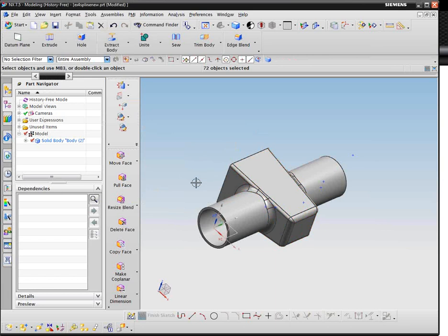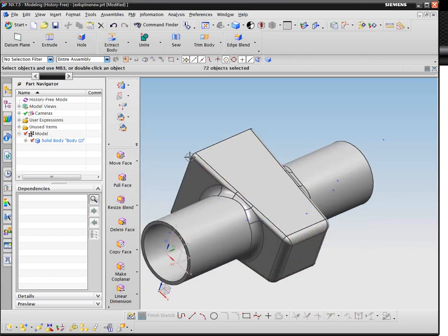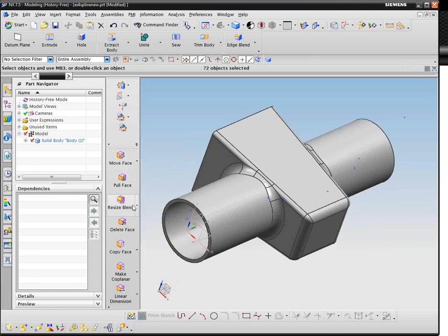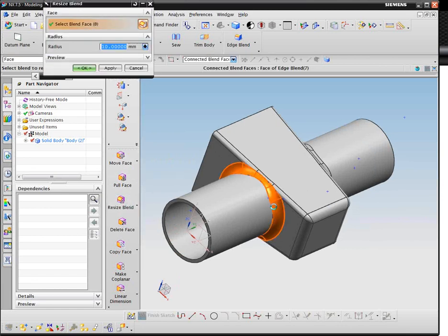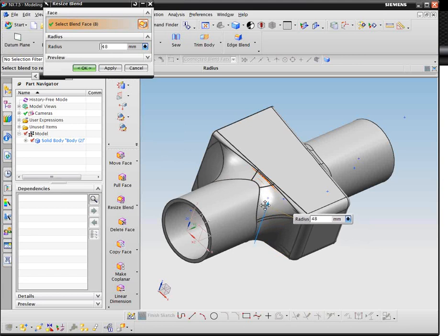It makes it beautiful, essentially. I'll just touch on the resize blend. It infers that the rest of the blend is all part of it too, so to change the size, here's a little handle to pull on. If you highlight it, it'll show you the directional movement. I can stretch it so it's tiny in that direction. I can push it this way so that it goes to its limits. It'll keep going until you don't see the preview anymore.